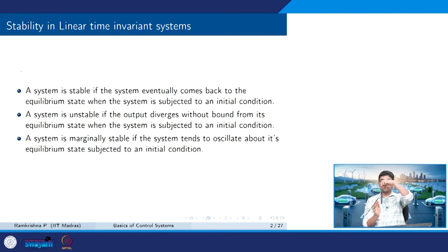Here, from the equilibrium I perturb it, it comes back to its original position. This is stable. This one, I push it a little bit, it just falls down. This is unstable. And a system is marginally stable if it just continues to oscillate like this forever. The oscillations don't die out, they just keep on oscillating. If the initial condition is larger, they will exhibit wider oscillations and so on. So that is the physics notion of stability.